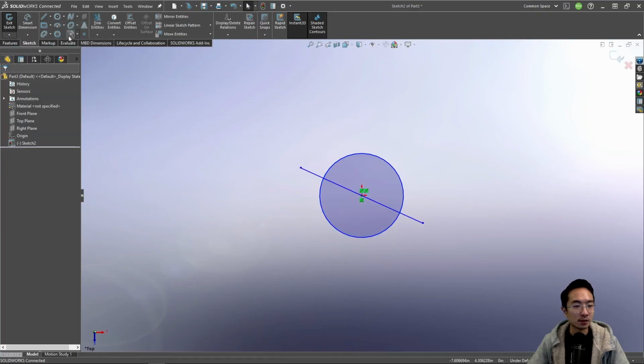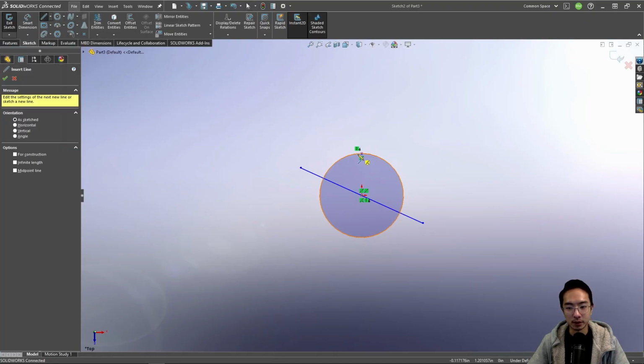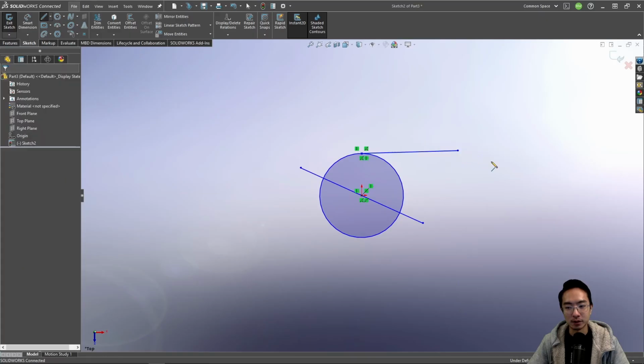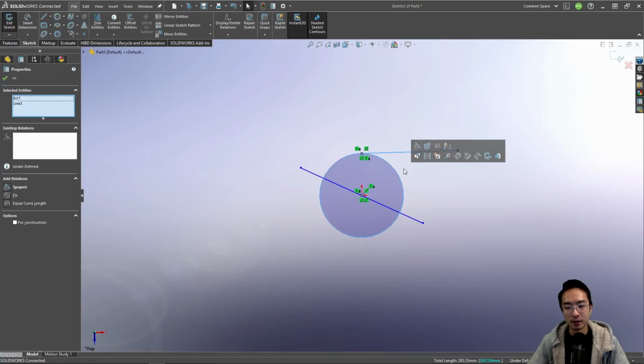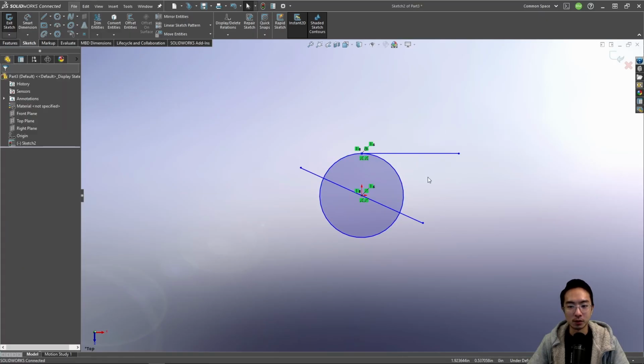Let's say you have a fancy circle and then there's a special point on here that you want to reference and you want to make that point tangent at that point or something. Then that's where creating that point might be useful. So points help you connect another sketch to another part of it, connects two sketches together at a very specific location. Sometimes it's hard for you to dimension it directly, but that's one common application of a point.